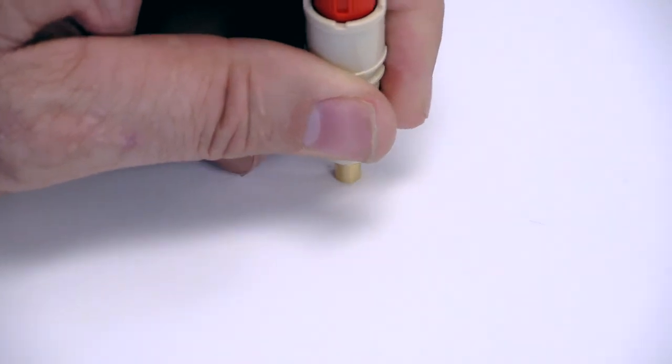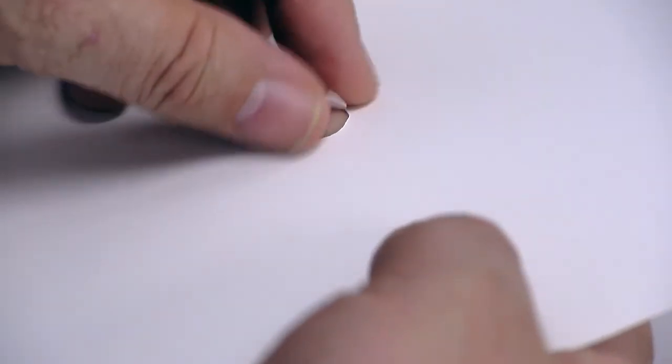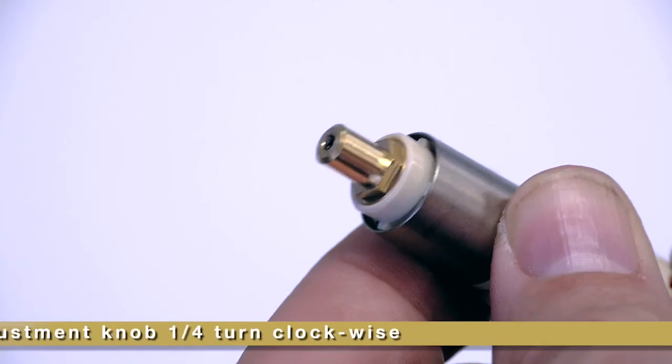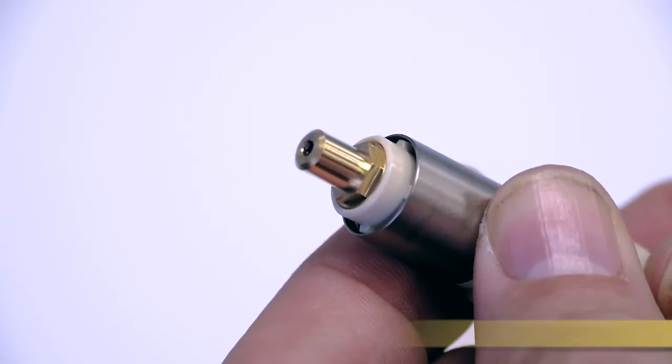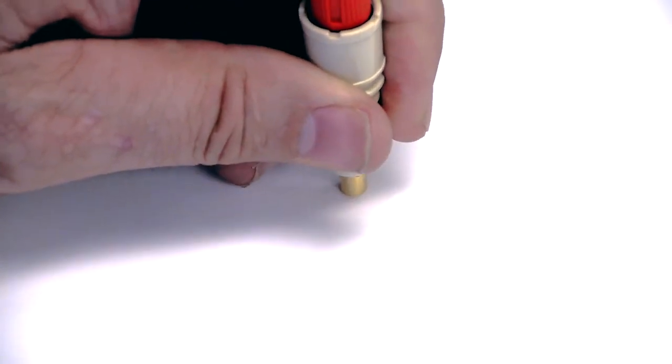Then, with the blade holder tool in your hand, draw a circle on the material. Go ahead and remove the circle. If it is difficult to remove, then extend the blade by turning the red adjustment knob 1/4 of an inch clockwise, and repeat the test.